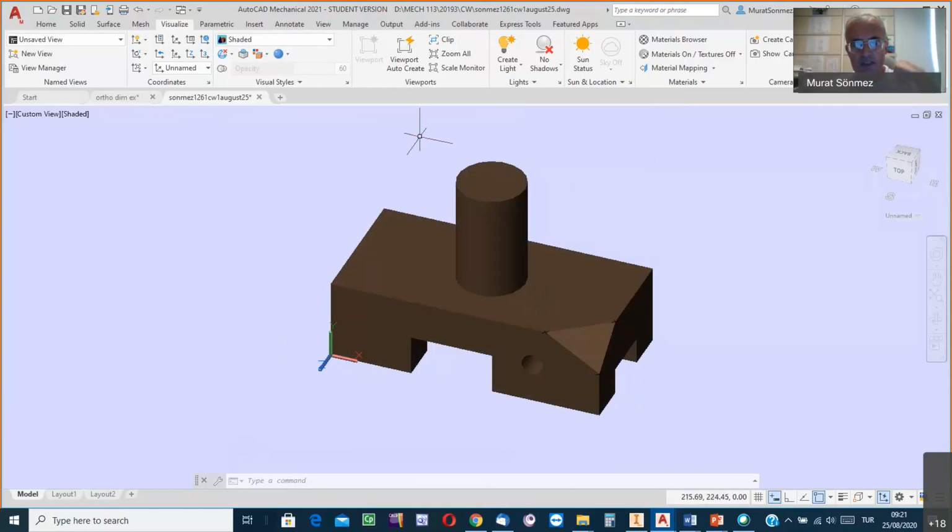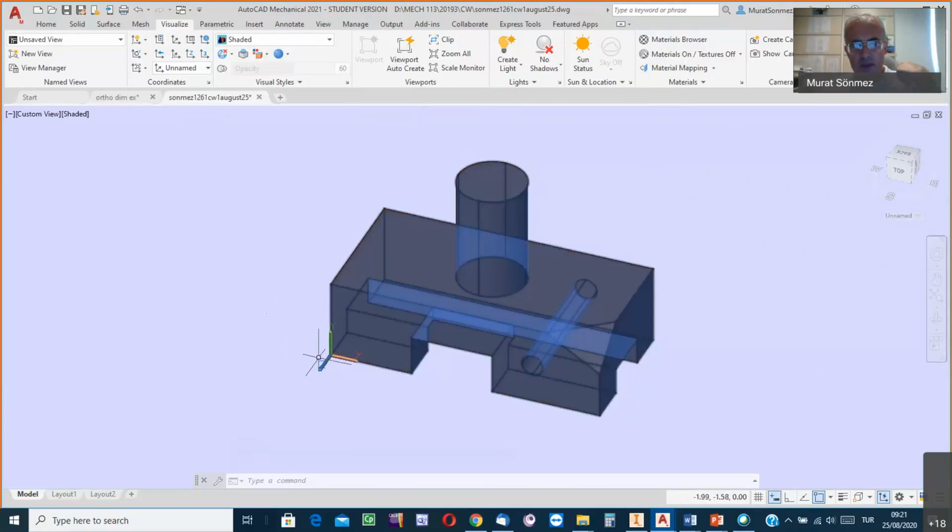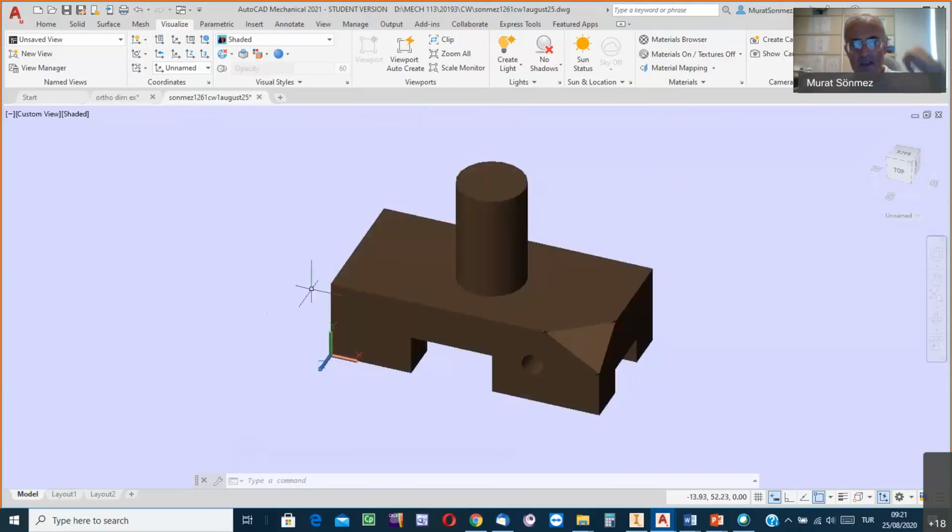In doing this, bring the coordinate frame to a characteristic point of the already created feature, and relative to that point, locate the characteristic point for the base of the new feature, and then apply the process. The other technique is this one.